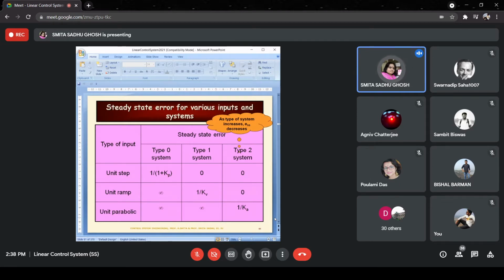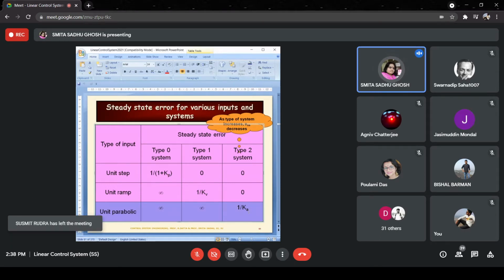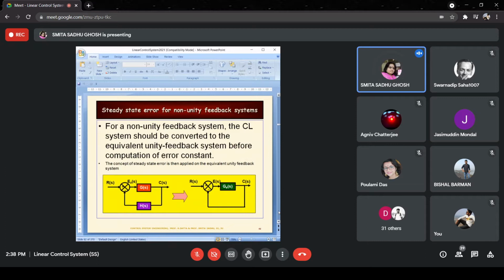But as far as the steady state error and error constants are concerned, they are defined specifically for the step input, ramp input, and parabolic input only. So the definitions of Kp, Kv, and Ka correspond to a step, ramp, and parabolic input only. However, the methodology that we adopted can be applied to systems with higher types, as well as if your inputs follow a similar pattern but have a higher order.